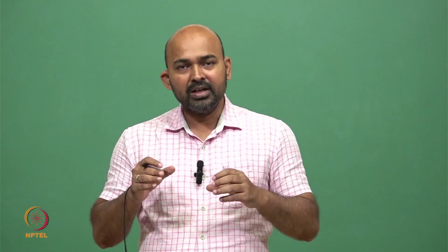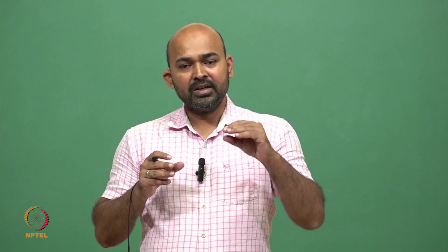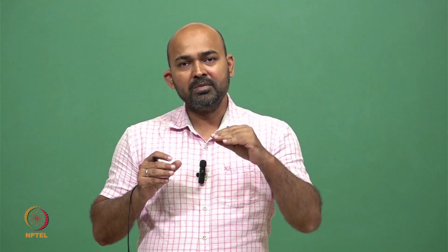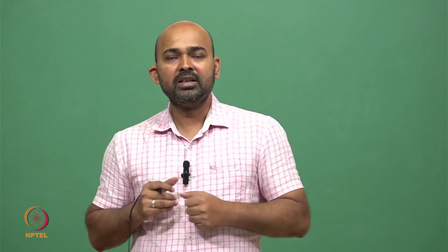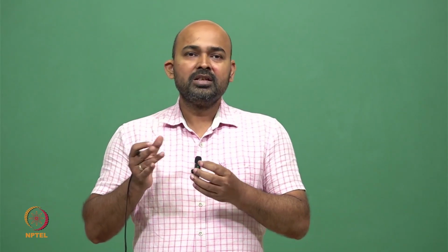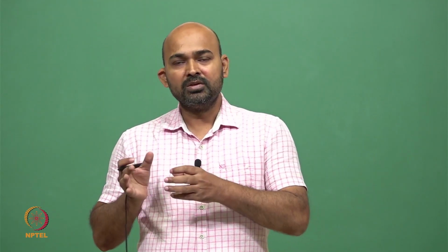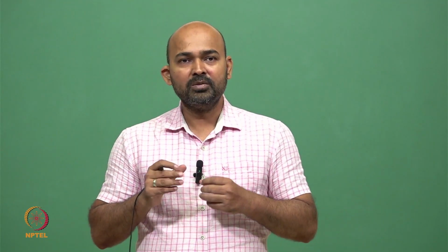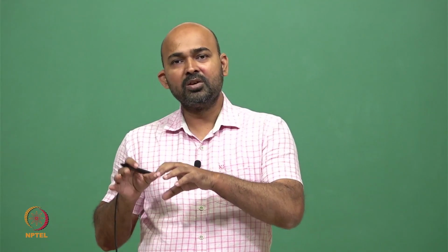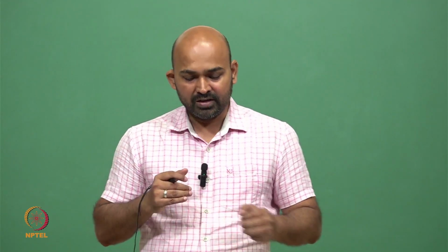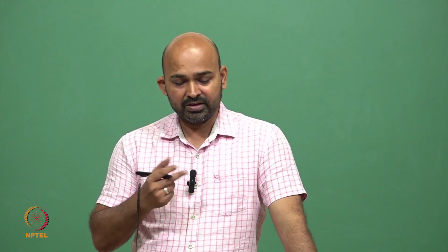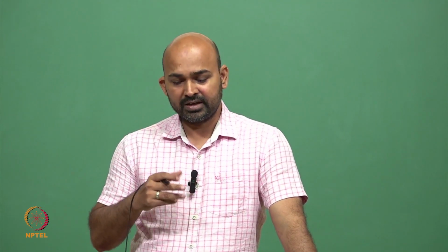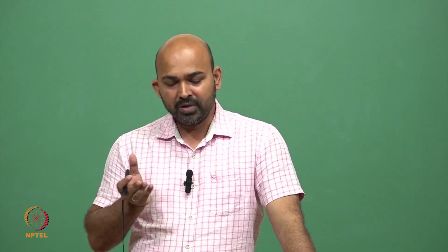In the solidly mounted bulk acoustic wave, this film is actually resting on different materials, and some amount of energy is actually lost to those materials itself. So that will change the quality factor to a degraded value, because some energy is actually being lost in the other material as well. So let's discuss what are these two types of bulk acoustic wave sensor. One is the film bulk acoustic wave, and the second is the solidly mounted bulk acoustic wave.